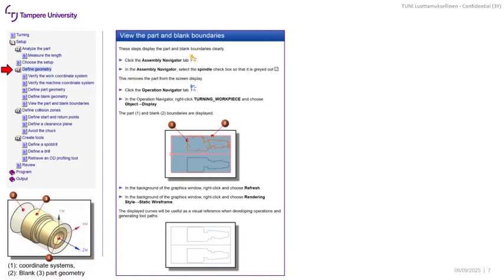So from this step, we are no longer working with the 3D object, but we are looking at the 2D object so that we can see different positions of the parts. Also, we can easily access visually the internal geometry of the part. For this, we need to go to the assembly navigator, turn off or gray out this box that I will show you in the software, and start defining different operations based on this static wireframe. So you need to change the rendering style to static wireframe.